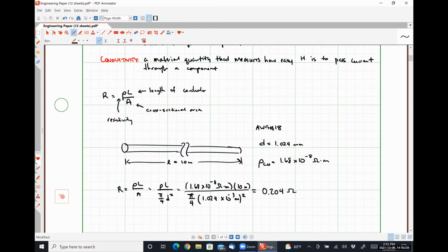What's the smallest resistor that you guys ever built a circuit with? Somewhere on the order of 200 probably in your Engineering 120 series, okay? In this class, we might do a couple of experiments that use, say, 10 ohm resistors and all that kind of stuff. But effectively, every resistor that we are going to ever build a circuit out of in this class has a resistance that is an order of magnitude or larger than the resistance of this incredibly long piece of wire. So in Engineering 120, you made an assumption that wires don't contribute any resistance.